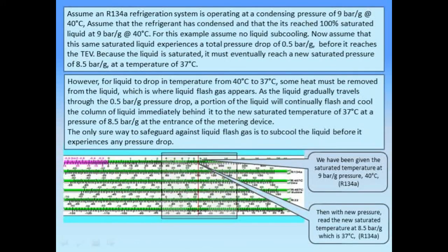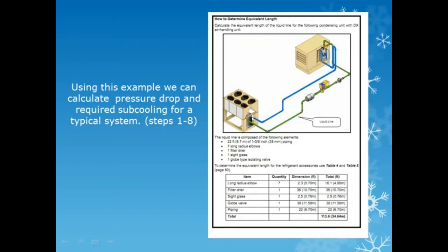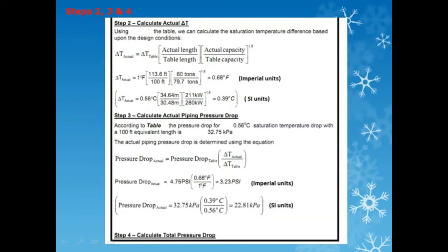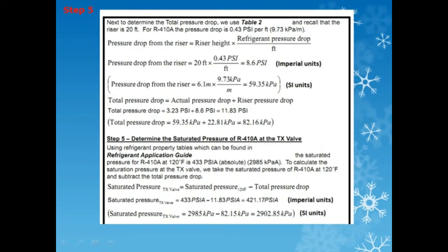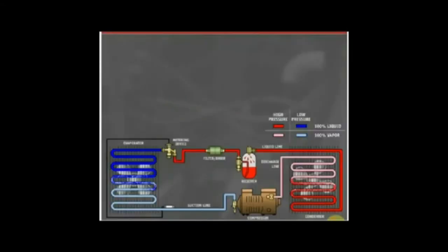Adding refrigerant to the system can increase subcooling, but this is usually not recommended because of added inefficiencies that may occur. There are several ways to subcool liquid refrigerant.